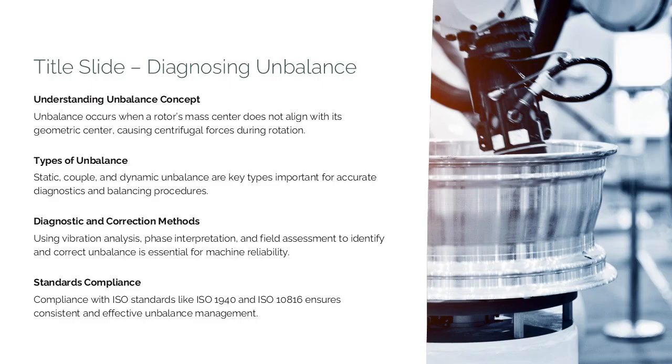Understanding the types of unbalance, static, couple, and dynamic, is essential for performing accurate diagnostics and proper balancing procedures. Additionally, the presentation highlights best practices in field assessment, correction methods, and compliance with standards such as ISO 1940, ISO 7919, ISO 10816, and ISO 14694. Each section will guide engineers through identifying symptoms, analyzing vibration signatures, interpreting phase relationships, and implementing corrective actions, forming a comprehensive view of unbalance management.